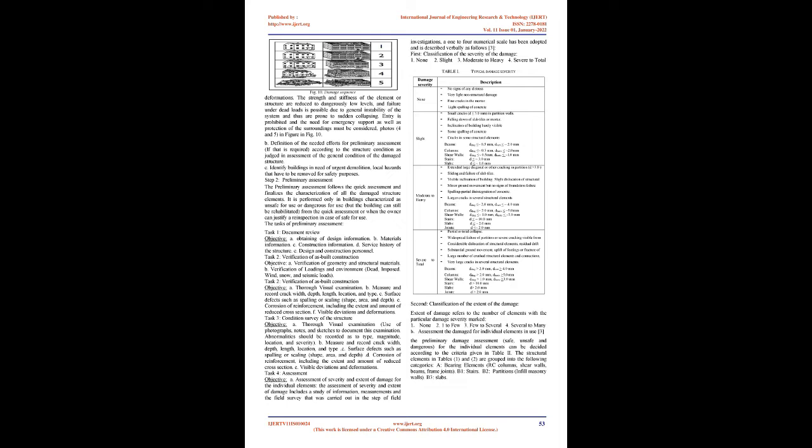Although some of them may also need emergency support, the risk when entering them for short periods of time, e.g. for removing valuables, securing contents of apartments, etc., is deemed to be low, but not negligible. It should be noted that buildings in this category present the greatest uncertainty in the classification. If the inspector has doubts about his evaluation, he should be conservative. Photo 3, in Fig. 10.